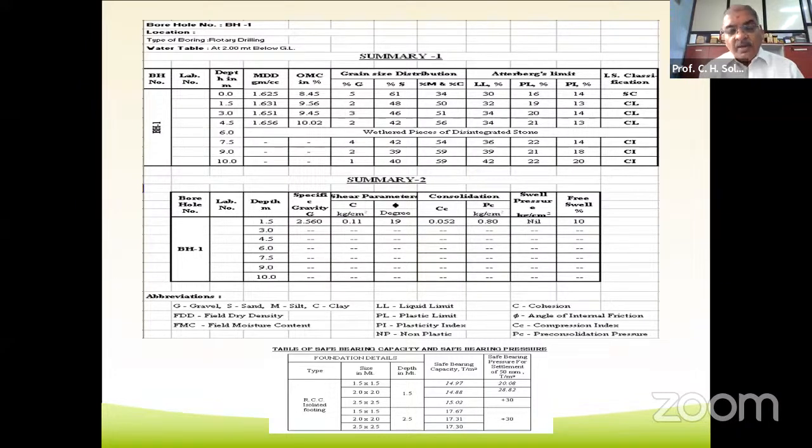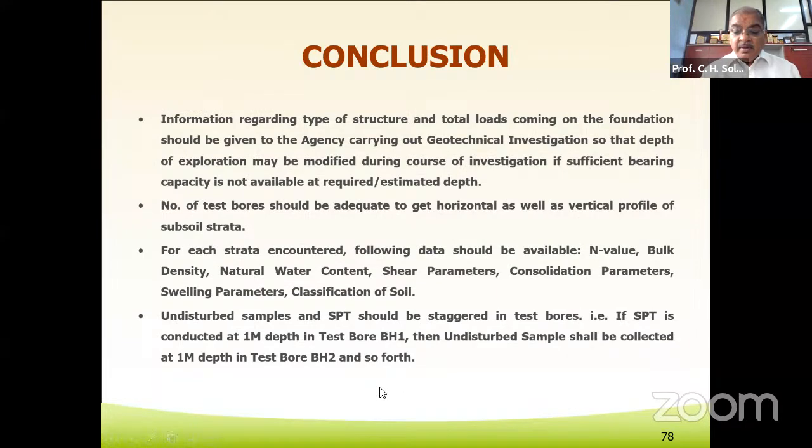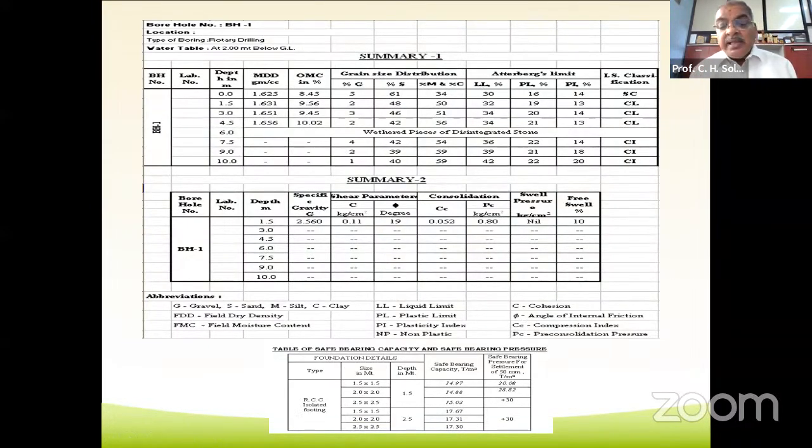The table given below in this slide shows the computation of the safe bearing capacity. Now, for different sizes of foundations and at different depths, the safe bearing capacity is computed using the IS 6403 equations, and the results have been presented here.